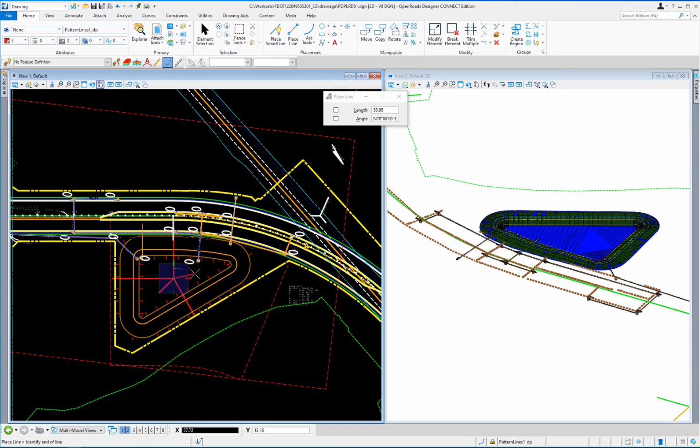Hover over the arc element that is in the right corner of the pond control shape until there is a yellow X at the midpoint of the arc. While the yellow X is visible, type R, then Q to rotate the AccuDraw compass and hit the Enter key on the keyboard to lock to this axis. Drag the cursor to the right so that it is near the green back of sidewalk line and left-click to complete the pattern line.